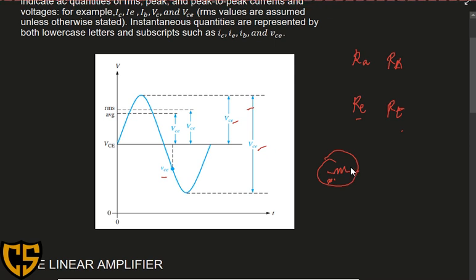This is your internal resistance, and its value is expressed in lowercase r, sometimes with a prime on top to show that it is an AC resistance. An example is the internal AC resistance of your emitter, r'e, which has a prime on top.